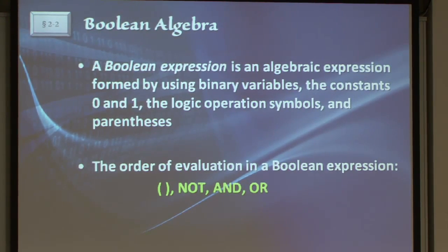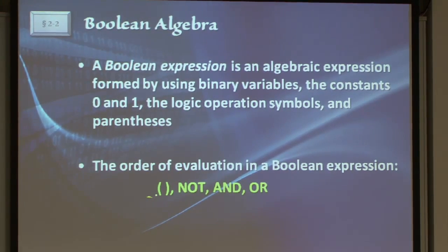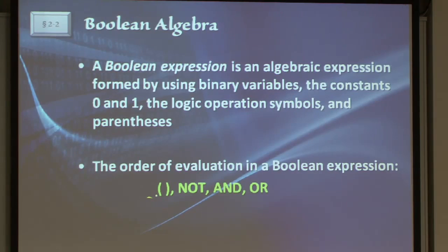Now with those operations, the parenthesis always takes precedence, followed by a NOT operation, followed by an AND, followed by an OR. It's very similar to what we do in mathematics anyway, so it makes sense. You don't have to memorize anything new. Let's take an example of some Boolean expression.